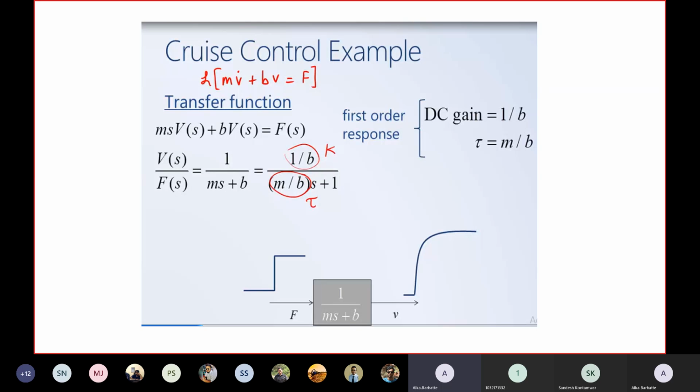The resistance that is opposing the velocity. So with this equation, we can now model it. It's very simple, a first order transfer function. That means a simple vehicle dynamics can be represented using a first order transfer function, and the same function we are going to implement to represent your cruise control. Is this clear, the transfer function to represent your vehicle?